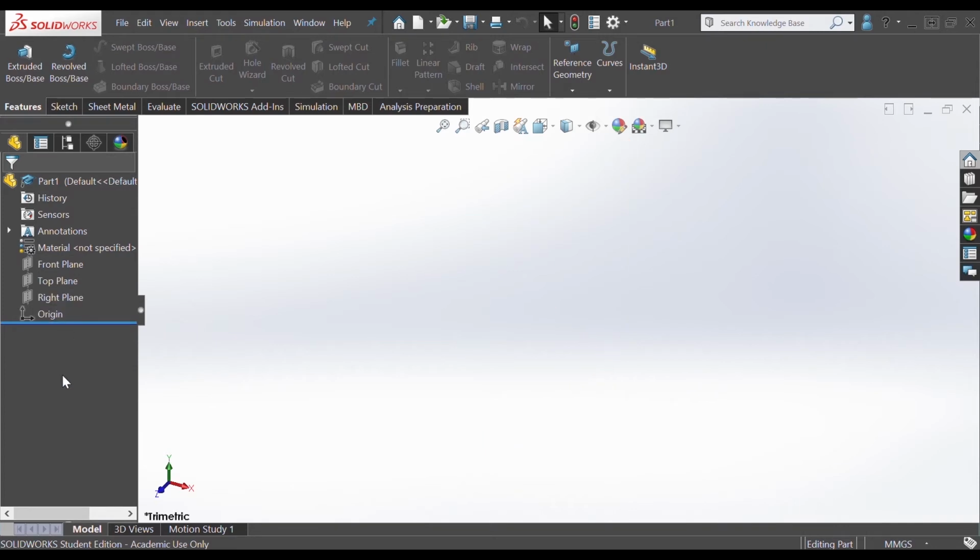You've got the origin, and anything you draw or construct in this graphics area is going to be recorded in this tree manager, which you can further add to, separate, and manage so it can be neat and you can operate on which part exactly. So if you draw a complex project and you want to break it down into planes, into objects, and into figures, and you want to make a change to one of these, you're going to have to go to the FeatureManager design tree, and you're going to find the specific part from these folders, and then you're going to change them easily.